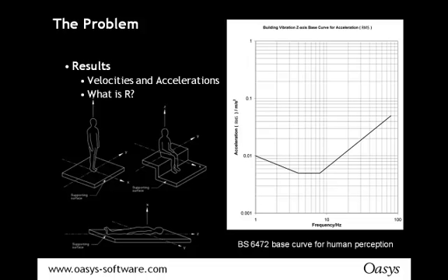If you're on a floor, people expect that to be solid, but if you're walking on a footbridge, then people are aware of walking in open air and therefore are more accepting of a certain level of vibration. So your actual target values vary from structure to structure and with your client requirements. Some clients, of course, have very stringent requirements, such as hospitals and laboratories, where you have to achieve some very tight vibration requirements.